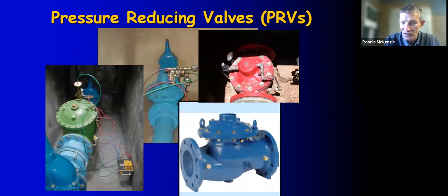These valves are designed to operate and run for a long time. As long as you service them regularly, they can easily last 50 years or longer. So there's no point saving 5% on the cost of the valve and putting in a piece of junk. So use a decent valve. There's many different manufacturers that all have different aspects. You know, they all have different widgets inside doing different things. We find that any of the good control valves will do the job if they're sized properly.